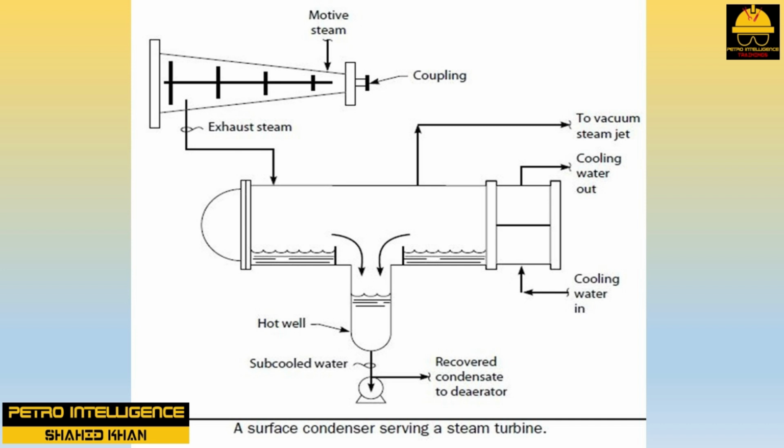The vapor outlet flow consists of air drawn into the system through leaks, CO2, and a small amount of uncondensed steam. The weight flow of vapor from the top of the condenser is 1% or less than the flow of condensate from the bottom of the condenser. The vapor is drawn into a steam jet. The steam condensate flows into the boot or hot well.